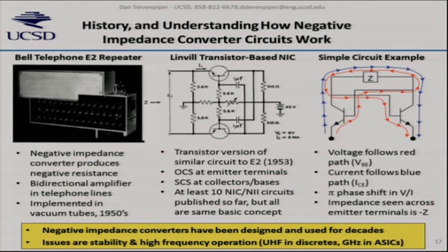The easiest way to understand it is that the voltages in these 2 transistors pass through the base emitter junction, so that's a constant voltage. If you were to trace the path of the voltage drops, it goes around along the red curve, passes through this model impedance, and comes back down through this base emitter junction.